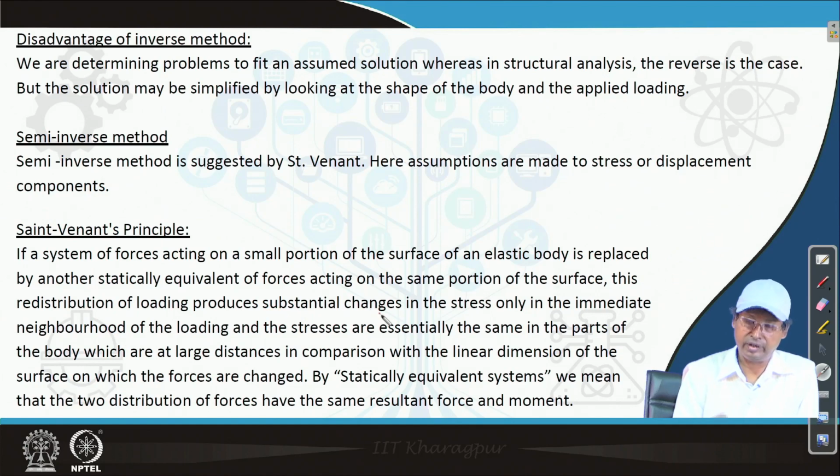It changes substantially, but in the intimate neighborhood of the loading, and the stresses are essentially the same in the parts of the body which are at large distance in comparison with the linear dimension of the surface on which the forces are changed.